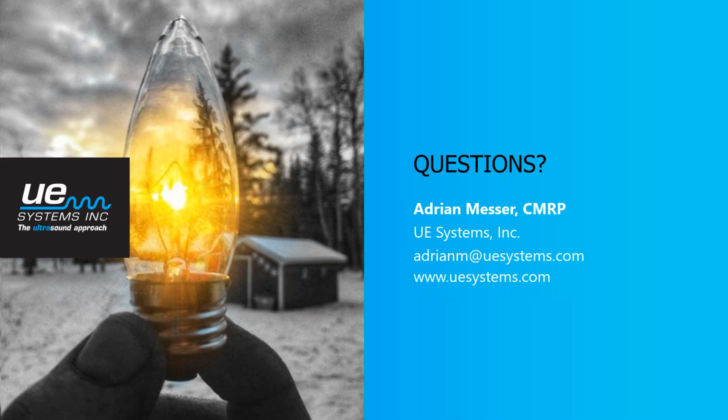Okay, awesome. And someone was wondering, back when you were talking about steam traps, how insulated a pipe can be to where you would still be able to pick up that turbulence. Yeah, that's a great question. Typically, the best place to make contact is going to be directly on the outlet or the discharge side of the trap. So, making contact with that trap or with the pipe that's closest to that discharge.